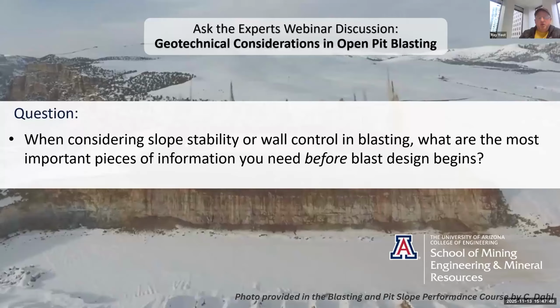This next piece is a bit of a chicken and egg problem, because you need to know how the rock is going to react to blasting before you start blasting it. But to understand it, you have to blast it a little bit. These are things like signature holes to get this sense of the waveforms, and if you had it, peak particle velocity versus scale distance graphs. Some of these are just fundamental pieces around how you start to design that blast, and the timing between holes and the impact it has on the rock, and all sorts of different things as well.